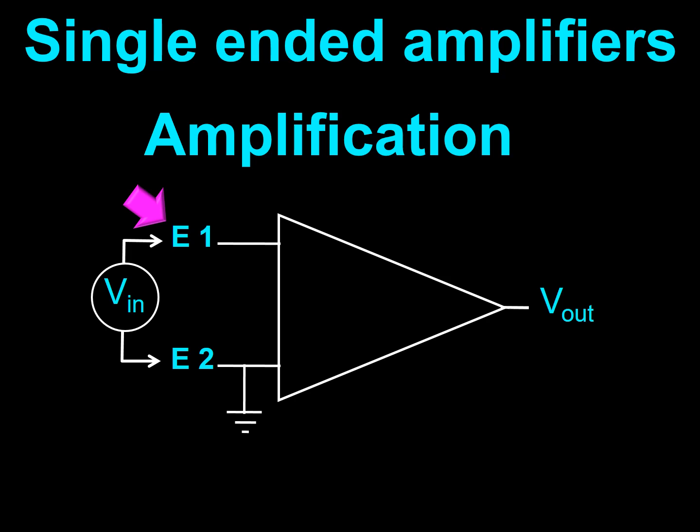We must remember that the voltage at E1 indicates the difference in electromotive force between E1 and E2. We must also remember that since E2 is attached to the ground prior to entering the bulk of the EEG amplifier, its value as far as the bulk of the amplifier is concerned is mathematically zero and electrically neutral.